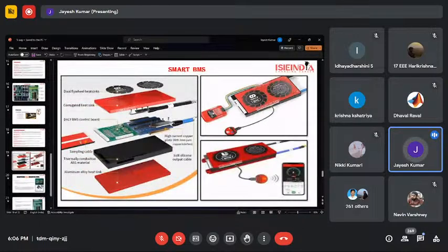In the smart BMS, there is a possibility to check the thermal power. Thermistors are also connected, and the CAN communications, or you can directly connect to your phone by Bluetooth, and you can see that each cell has a voltage, and how much output voltage you are getting from the battery pack. So this feature will help a lot for project work and the research part also.